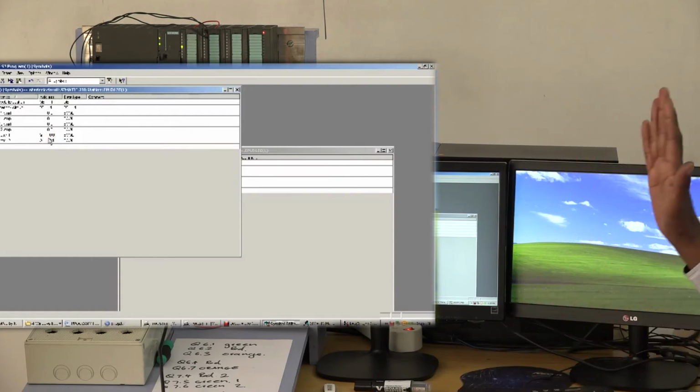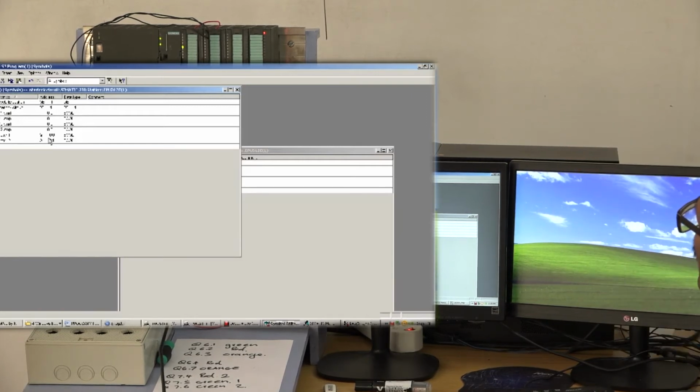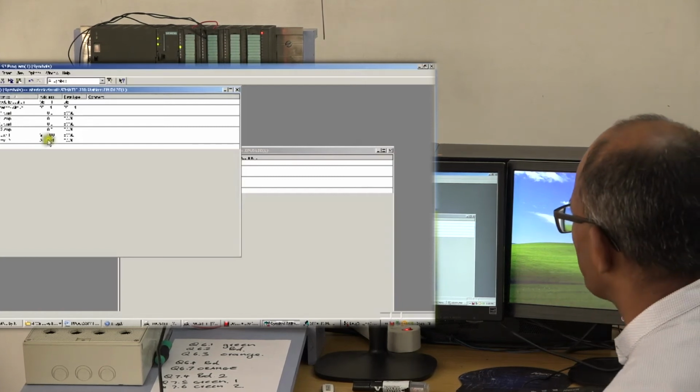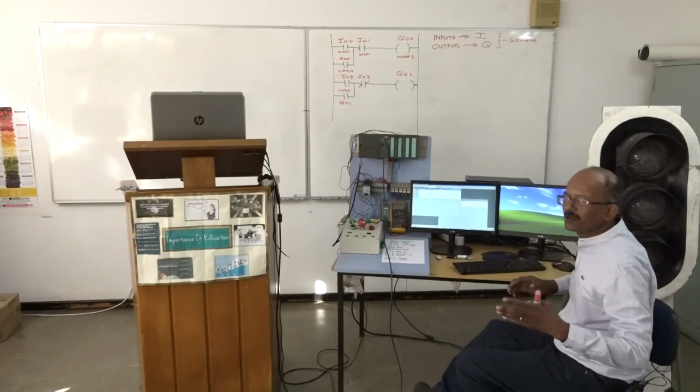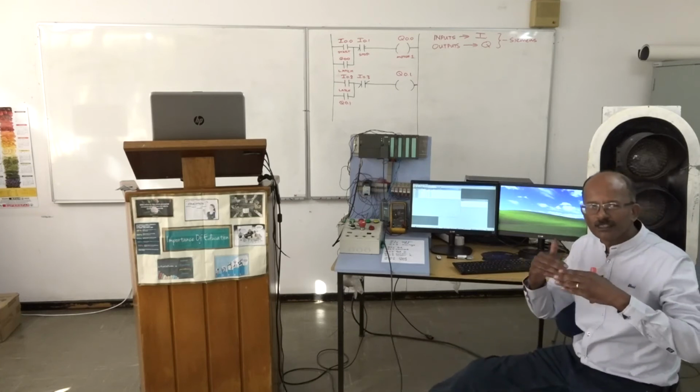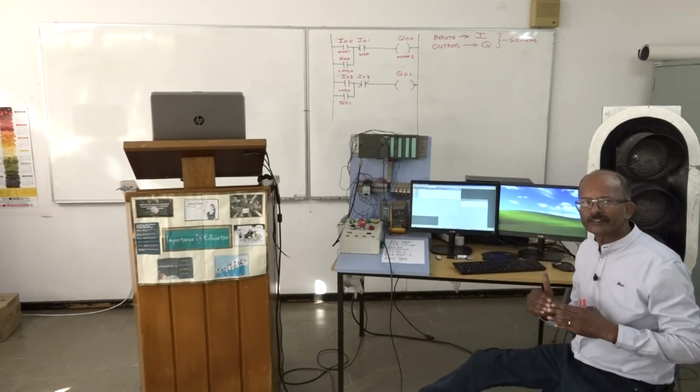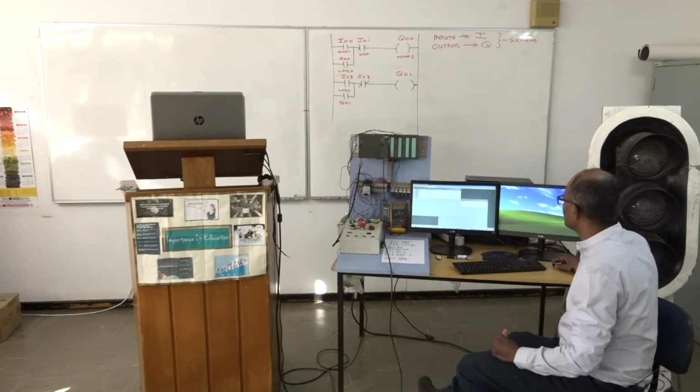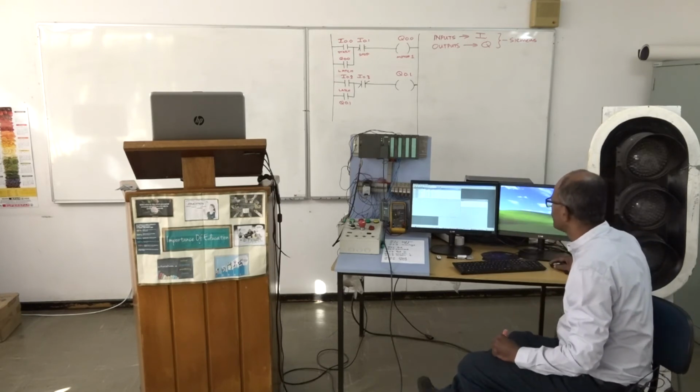Okay, so those are basically the 6 inputs and outputs that I have. Remember, Q0.0 and Q0.1 are auxiliary switches, so I don't need to put them in my symbol table. The beauty of this is when you are programming, these symbolic names will come up automatically with your addresses, and it will assist you with the actual programming sequence. So save. I'm going to now close that.